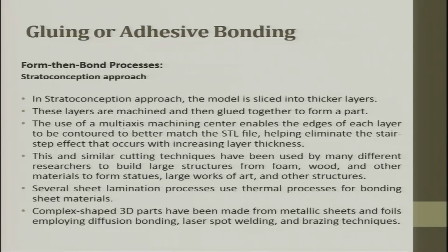The use of a multi-axis machining center enables the edges of each layer to be contoured to better match the STL file, helping eliminate the staircase effect that occurs with increasing layer thickness.